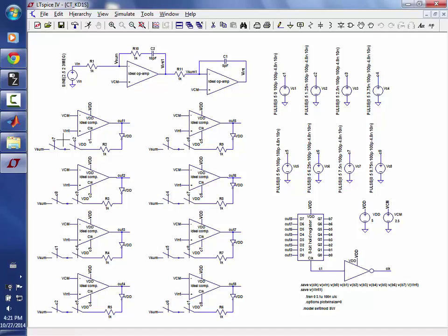So the clock phases here set the widths of how long those switches are on. So it sets the amount of charge that you can feed back into the integrator. In the ideal case, let's say there's 8 paths. Both of these switches are on at 1/8 of the clock frequency, so they're controlled with different phases of the clock.